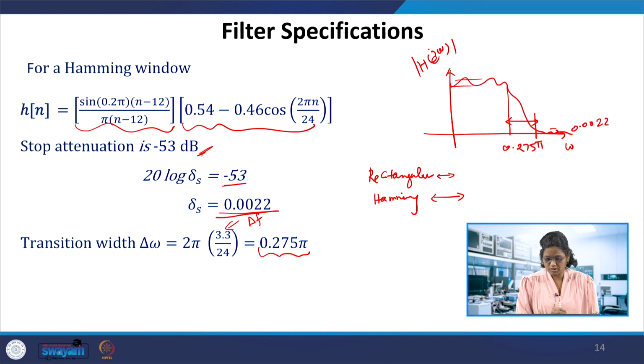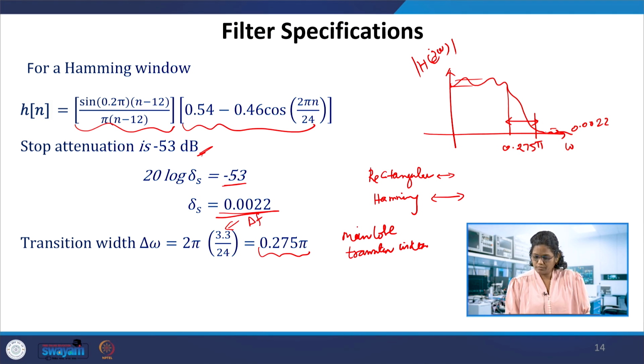As we discussed in the previous lecture, it is because of the relation between the main lobe and the transition width. The transition width and main lobe are directly proportional. The main lobe increases as we go for the tapering windows, but the side lobe level is reduced. The attenuation is good, and the ripple amplitude is very small here. If ripple attenuation is the focus, then keep that window and adjust the number of samples in the window function. So this is how it could be managed.